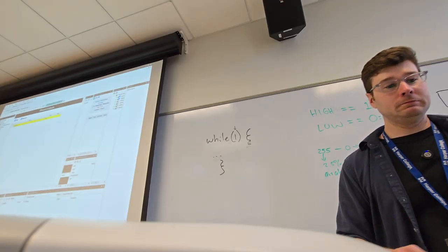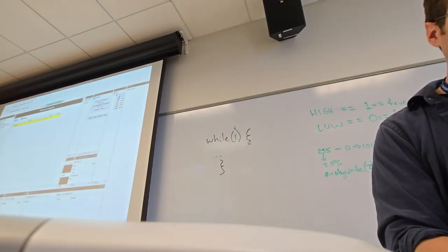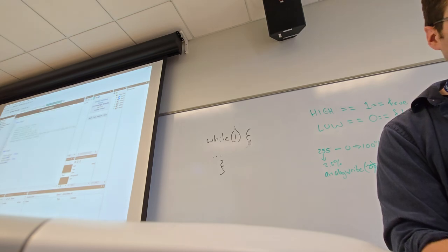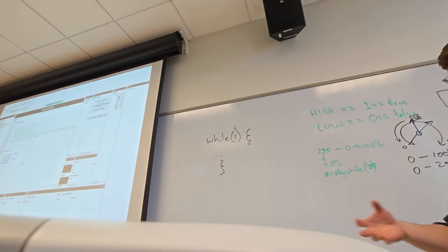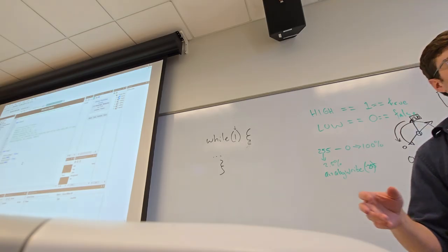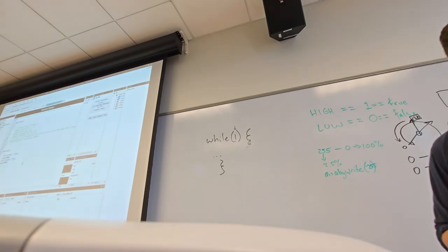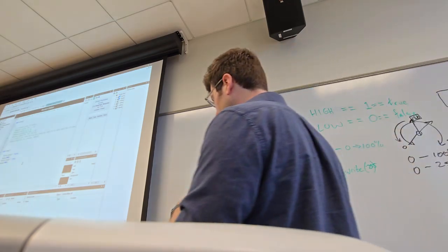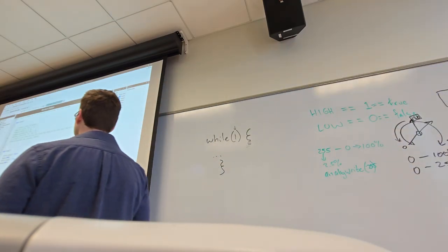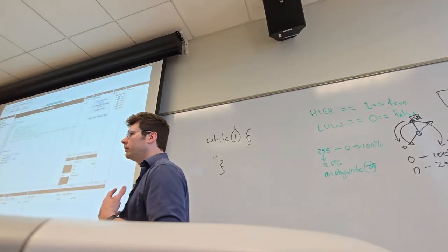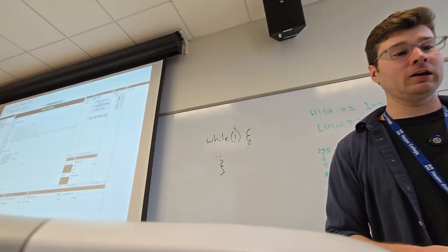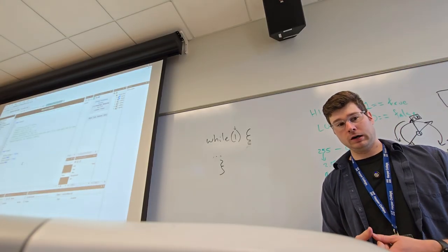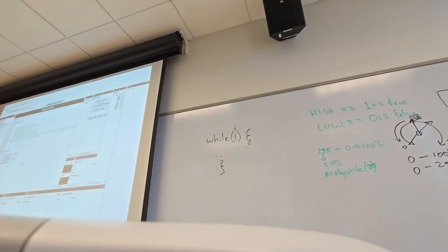But the benefit being that we can also handle networking here. We can exchange information through Modbus, and stick it into places or act on that information. We can get or post information over the internet if we're talking to a server, or if the PLC is acting as a sensor and giving information off site. That could be done over Ethernet or through Wi-Fi. That is also something that could be done here, and there's documentation for doing so online.